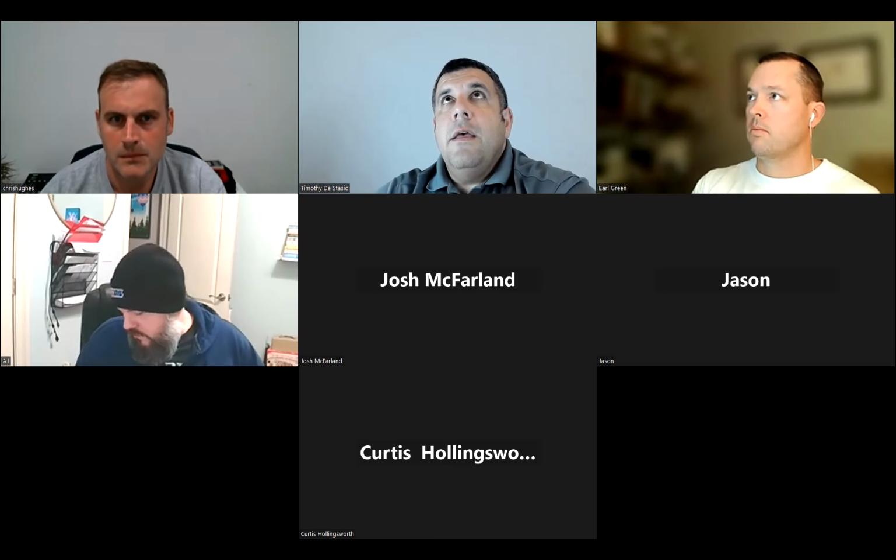Joe Stiebrick says that he thinks ASHRAE 62.2 is a little bit overkill for continuous ventilation. He suggests maybe continually ventilate half of that, but have the capacity to ventilate up to 3 times of that on demand. And I agree with that.